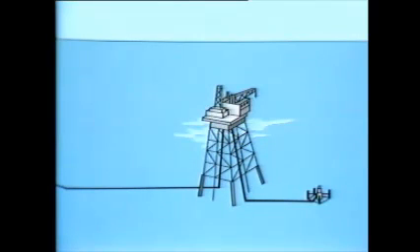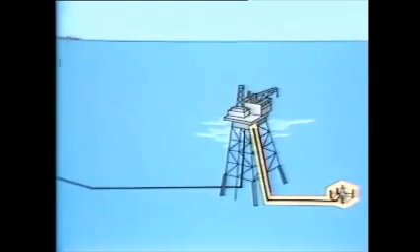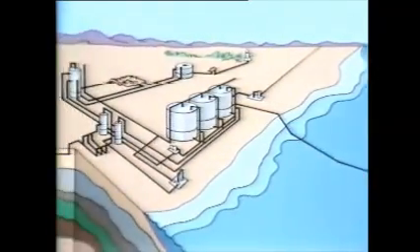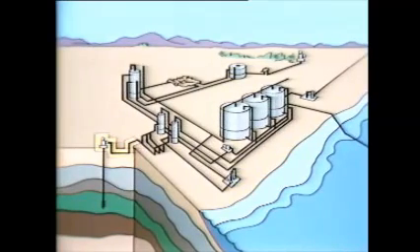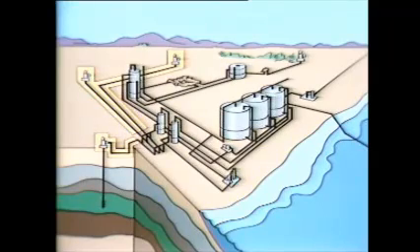The produced fluids leave the Christmas tree and enter a surface flowline system, usually a 2 or 3 inch pipe, which may be on the sea floor for subsea completions or below or above ground at onshore installations. If the production facilities are shared by a group of wells, as is often the case, the flowline will probably connect to a header or production manifold.